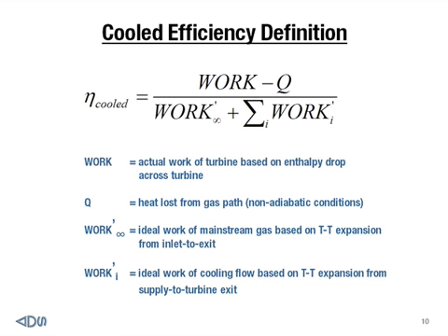And that, in total, forms the definition for cooled efficiency. Again, if it's adiabatic and there are no cooling flows, the Q goes to 0, the summation terms go to 0, and you have your classical textbook definition for efficiency.